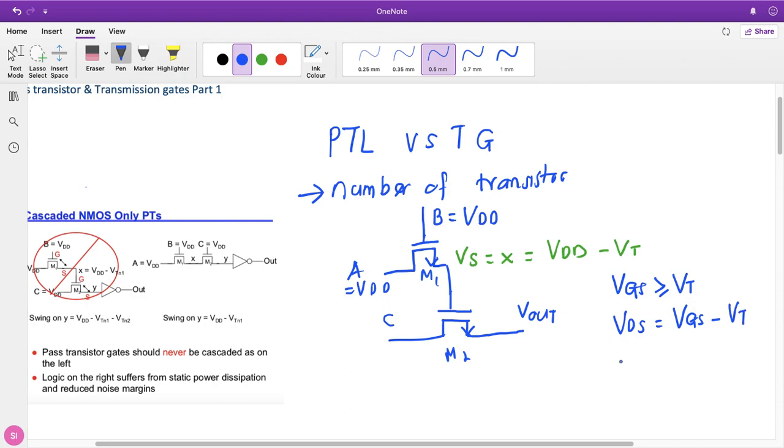So for this example, VD is set to 2.5 volt, for example, at VDD. So I can call VDD equal to 2.5 volt. Then the Vgate is also 2.5 volt, minus VT, which here I claim as 0.43 volt. So this example shows that VD is larger than 2.07.